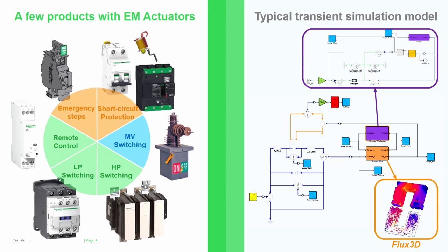In purple, we have the mechanism. As I said, it's a very simple linear mechanism with two end-stop sliding mass built with Modelica. To take into account the resistive force, the load curve, we use just a table lookup and some friction. And of course, we have the feedback loop for the back EMF.